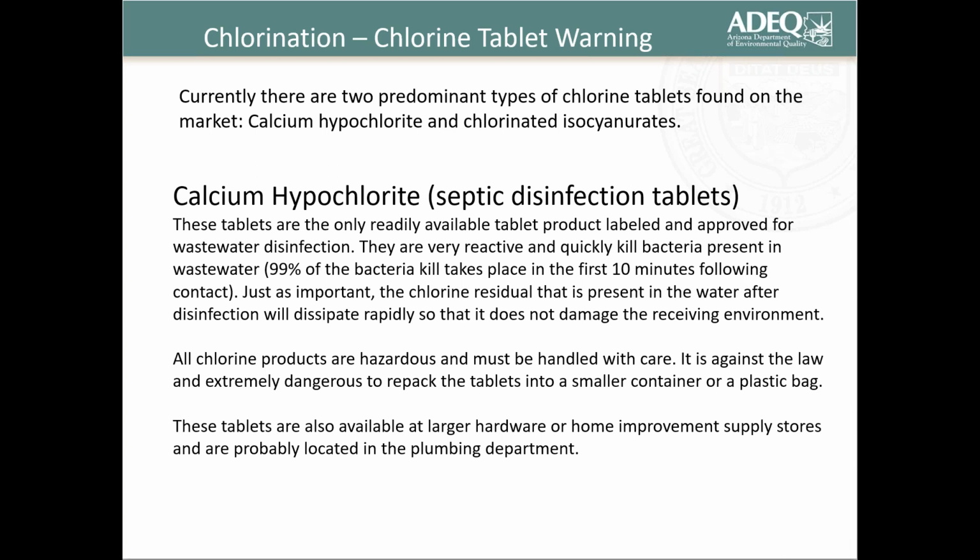They're very reactive and quickly kill bacteria in wastewater. 99% of the bacteria kill takes place in the first 10 minutes following contact. Just as important, the chlorine residual that is present in the water after disinfection will dissipate rapidly so that it does not damage the receiving environment. And I would say dissipate rapidly is a qualitative term relative to the pool tablet.